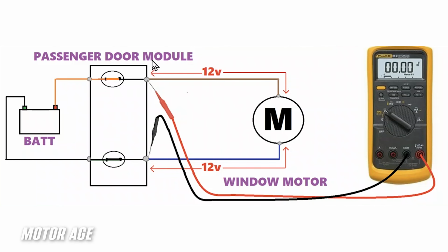So the fact that I verified I have 12 volts available here and 12 volts available here infers to me that this circuit is complete. It doesn't prove the motor is healthy. It just proves we are not dealing with an open circuit upstream of these connections right here. The problem is between here, where we measured, and battery ground. And of course, that's where we found two problems.